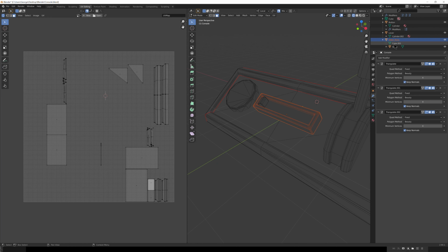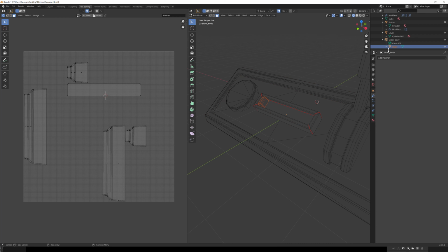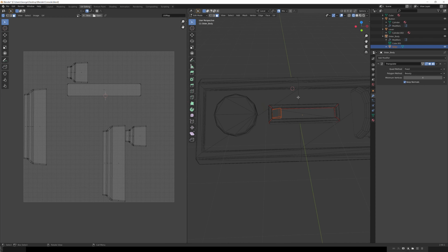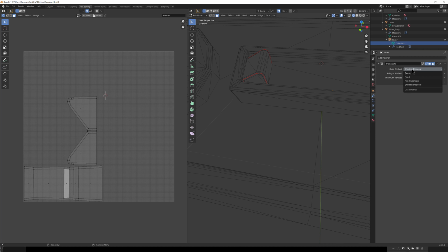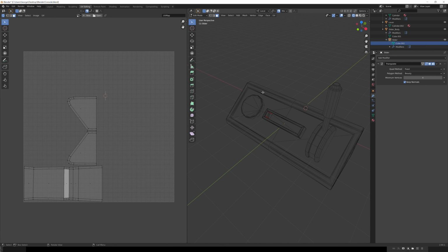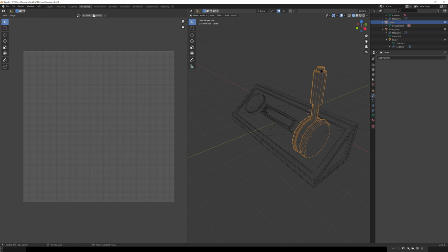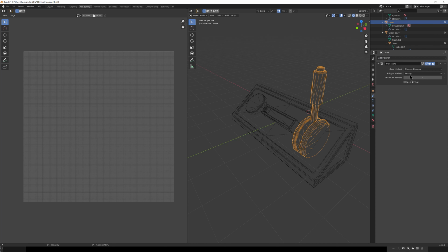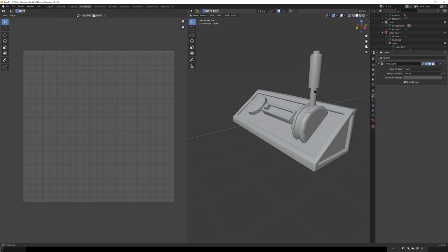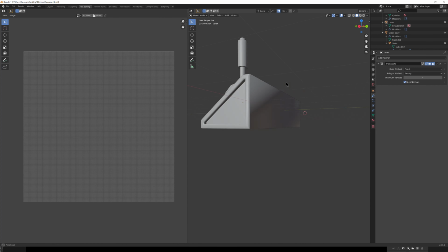And we're going to open up the slider body now and go to the slider itself. And let's triangulate that as well and choose what we want. There we are. I've now triangulated my entire mesh and everything looks, well, about right. Oh wait, we forgot our lever. Let's make sure we do that. Triangulate and Fixed, Keep Normals. All right, just take one final look at it and I don't see anything bad.